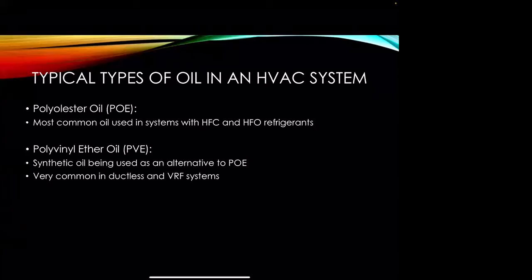Right now, there are also other refrigerants out there that Daikin and other manufacturers are using. So Carrier's plan, last I was informed of and educated upon, is going to be R454B. I would bet that they're probably going to have this PVE oil and not the POE, but they haven't announced yet which oil is going to be in that refrigerant. So we shall see.